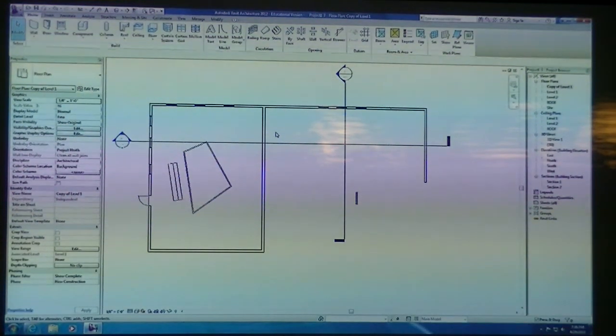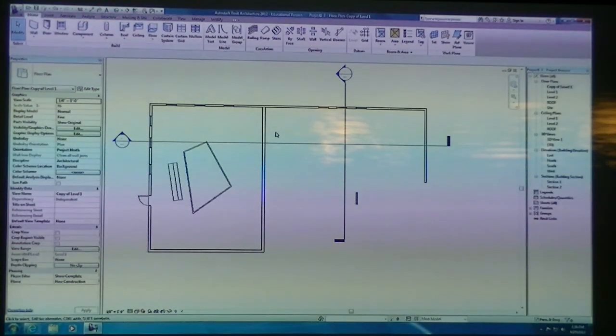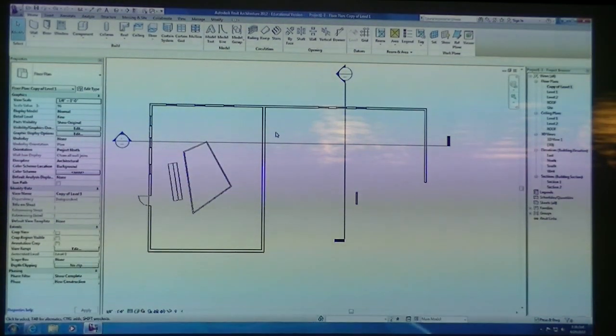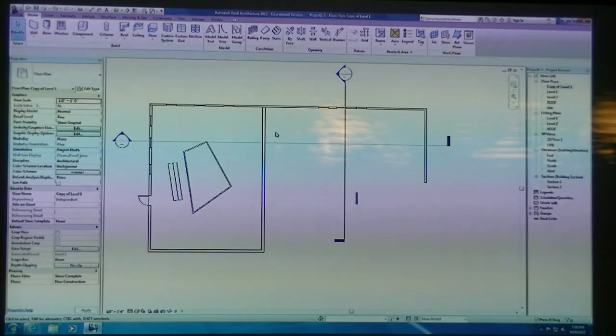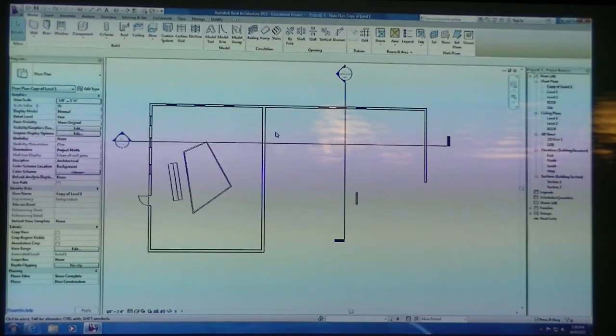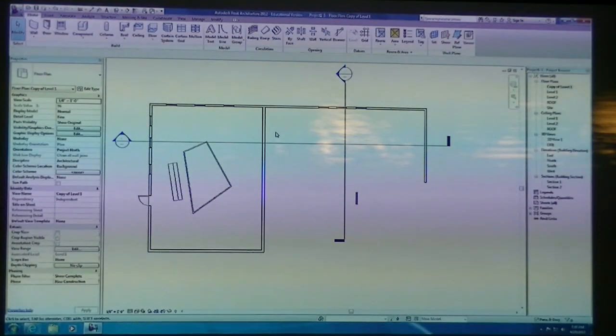And what you would do in CAD is you would do a save as of your file, where you would copy your drawings off to the side and manipulate them a little bit more. Well, in Revit, especially if you've got like an 80 meg file, first of all, you don't want to do that, because if you've been working with a group of people in your office, remember, more than one person can work on a file at the same time.